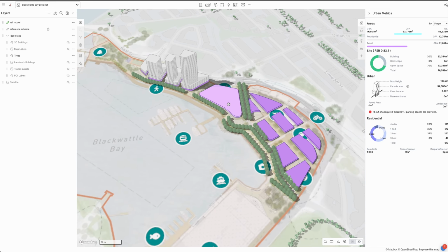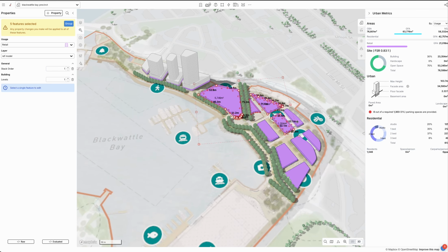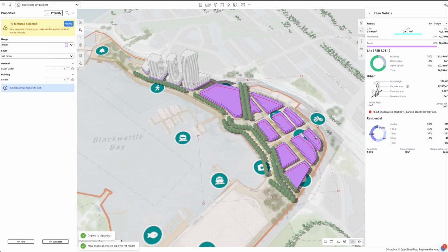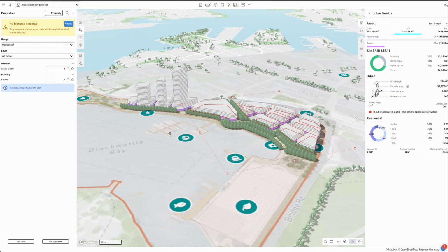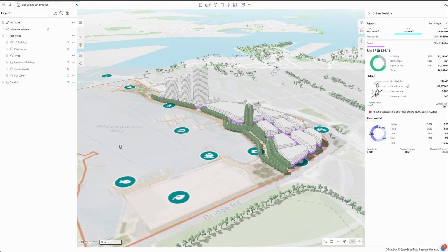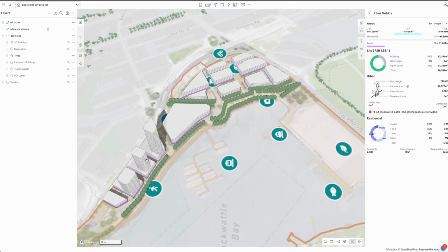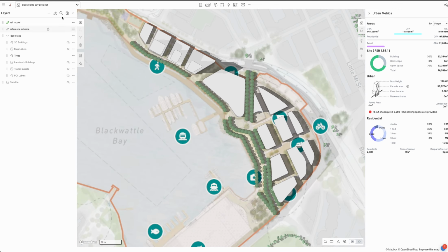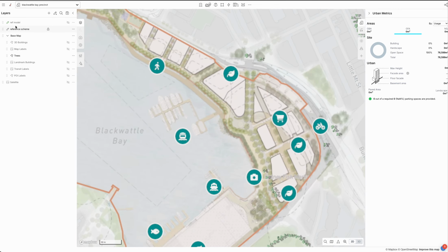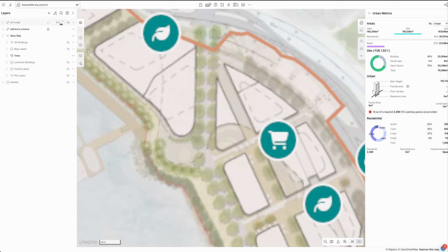Okay, so now I guess what we can do is just copy this all up. Hold Ctrl V. E to increase the stack order, increase the number of levels to 3 and change it to residential. Done. So now we've sort of done our base level. And then we should commence with our towers. So I'll turn the ref model down again. Not to 0, but to like 6.